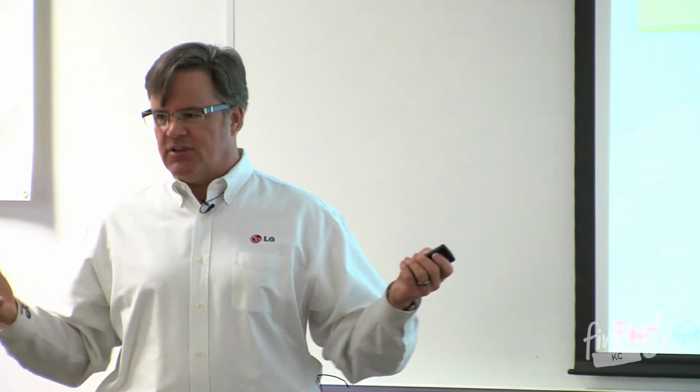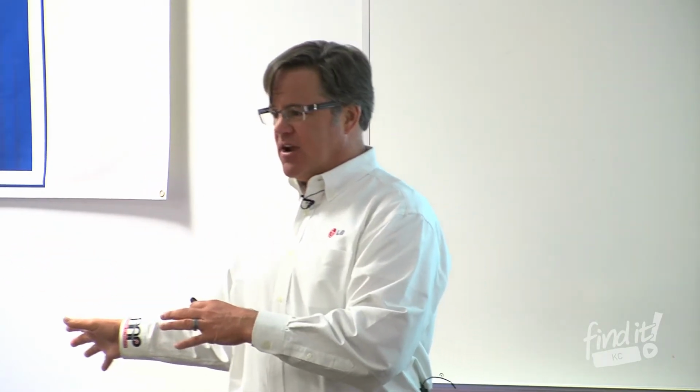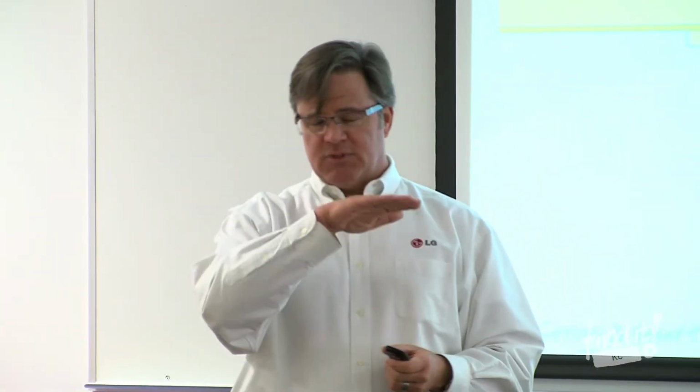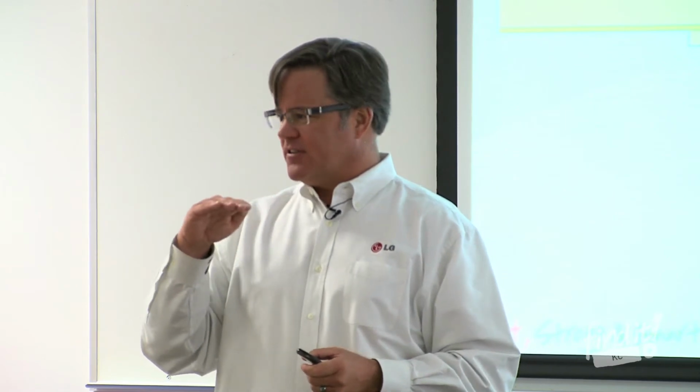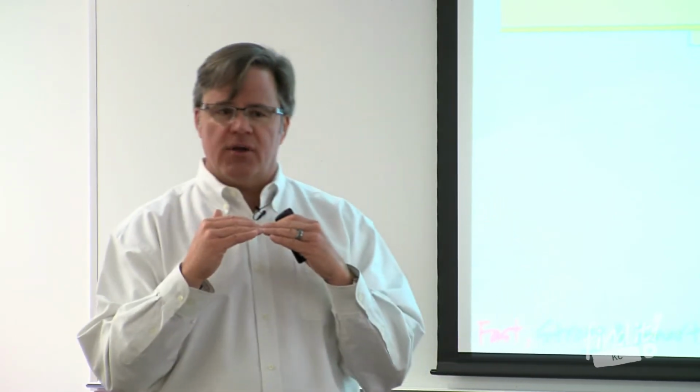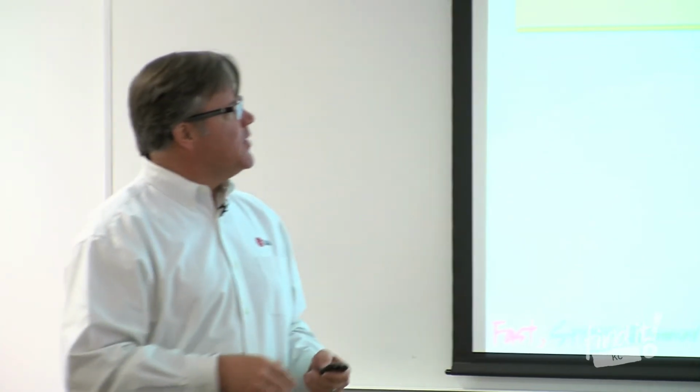One of the things that we noticed, as Rex said, we have a live lab, our office is VRF. And one of the things that we all noticed, being a bunch of hot-blooded guys, is that we love our houses to be in the 68-degree range. And because our office is drier than what our houses are in the summertime, we noticed that 72 is pretty chilly in our office working with VRF because it's always drawing moisture out of the air. So it's been interesting to experience that.